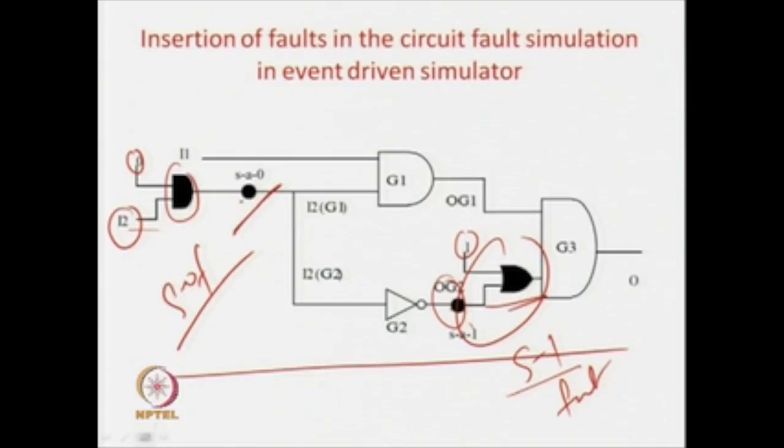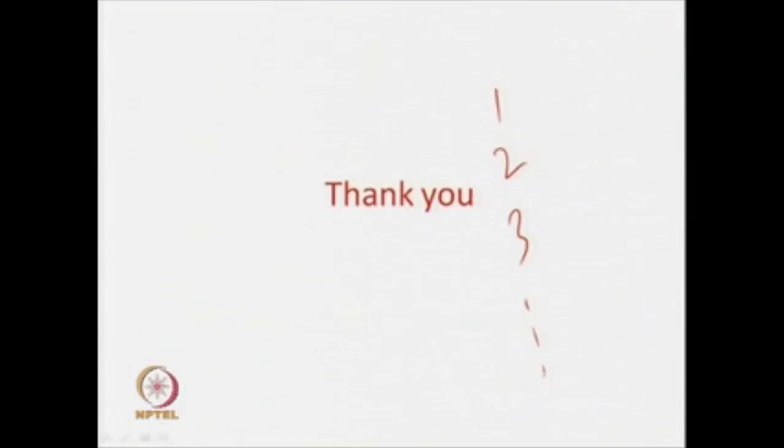So, with this we stop today, and what remains is for the next 2 lectures in this fault simulation series. Here we have improved on fault simulation by not using compiled code. We have a better technique called event driven simulation, but still our faults were serial. We took fault 1, fault 2, fault 3 and so on for a given random pattern.